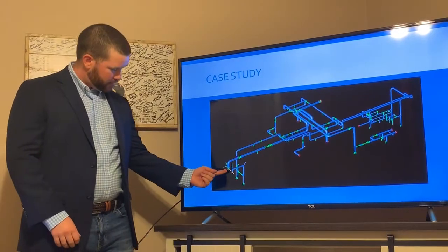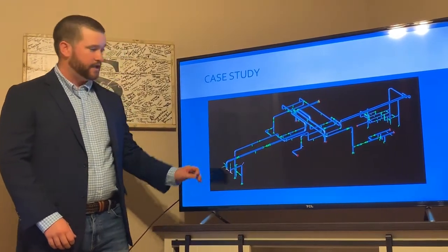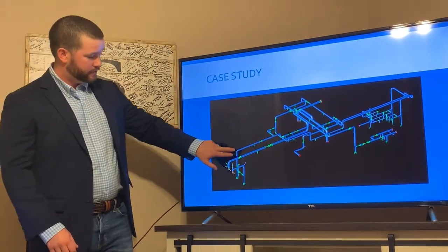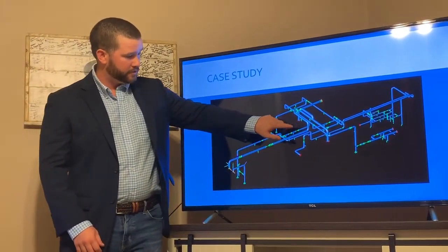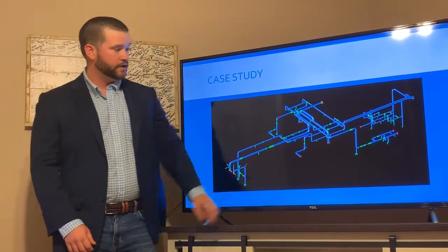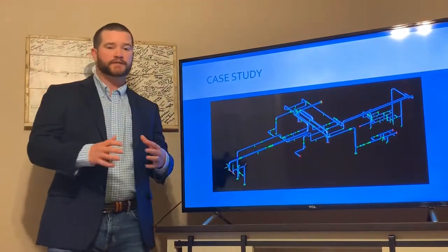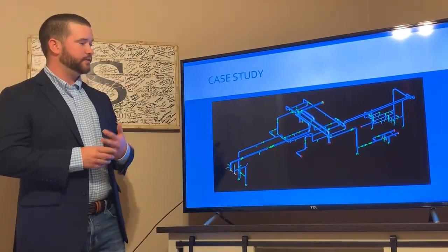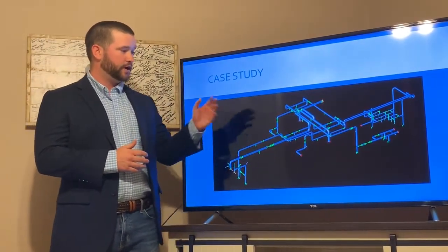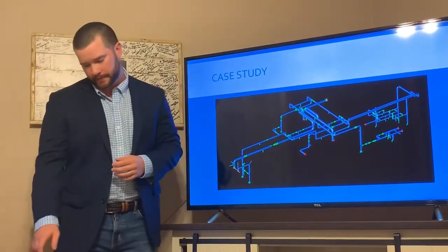We actually have a pump here. This is the suction and discharge nozzle of our pumps. And our system is strictly this pipe running from the pump, and it comes up here and runs into a pressure vessel there. All the rest of this is existing pipe that just happens to interface with our pipe. So in order to get a realistic picture of what our pipe is doing, we have to include all this to see how it affects our pipe.